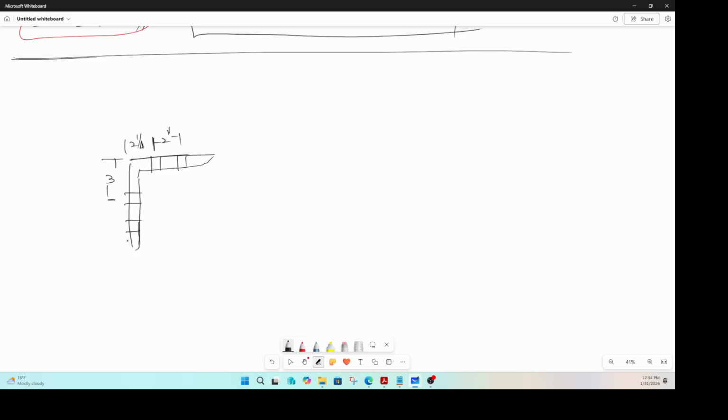Okay. So the angle on the left side is connected to a gusset plate. The right side on the top is connected to a gusset plate. And this angle is an L 8 by 6 by half. So one leg is 8 and the other leg is 6, and this is a half inch thick angle.